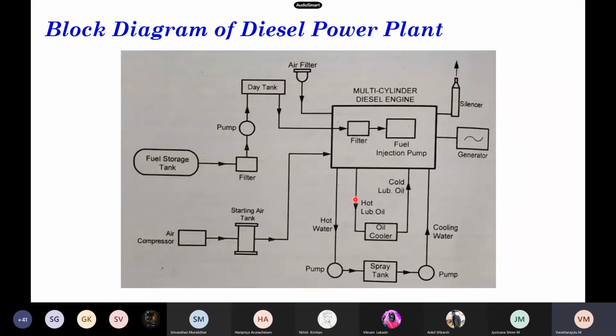Here that won't be a matter, and it can respond in a shorter time for varying loads without any difficulty, because we have a governing system, and fuel handling is easier, and there is no problem of ash disposal in the case of a diesel power plant. The plant is smaller in size when compared with the steam power plant. The space required is also minimal.